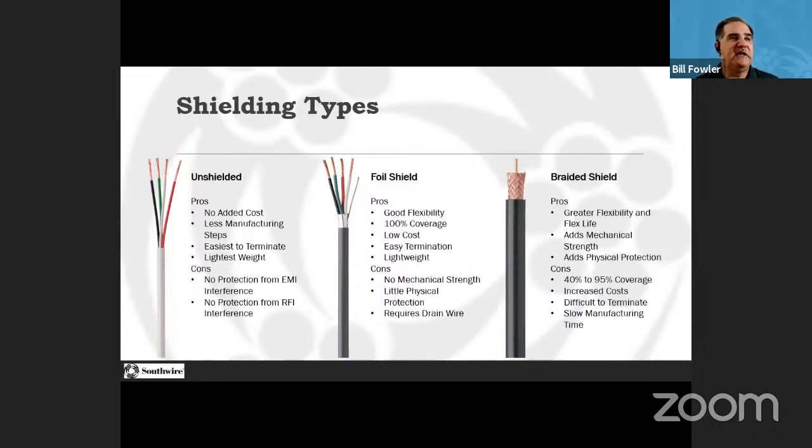So when you usually see data cables in Europe, it's a shielded twisted pair because their power is in open tray. So there's a lot of EMI in the ceilings in Europe, even in Canada. We see some in South America. So when data came along in the early 80s, they had to do a shielded cable to protect from all that open power. They don't put their power in conduit, so the data cable was more able to pick up that EMI, so they had to go to a shielded one.